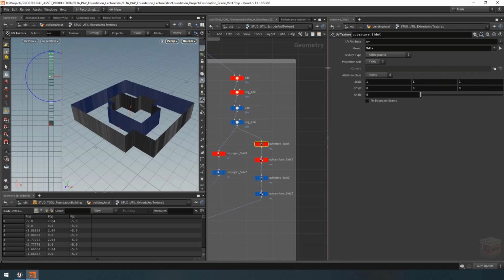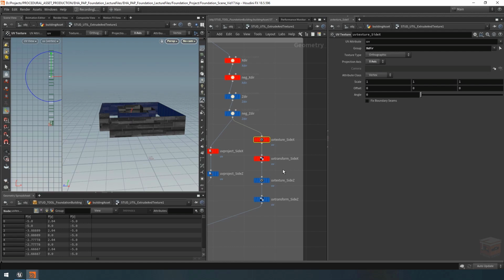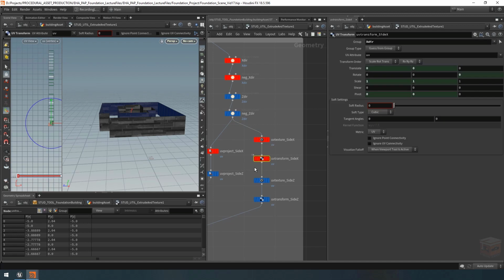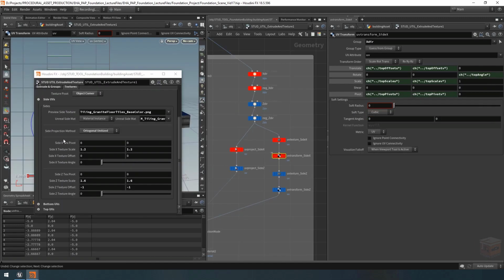So we are going to have to change our projection direction. In this case, we need to change it to the X orientation. So that works. And then over here, we don't need to change anything. But inside of our transform node, we do have to change these. So let's switch it over. Let's grab our parameters again. So I'm just going to grab from over here our pivot, plug that into the pivot, overwrite that. So it should be side pivot X, U, and V. Then the scale,